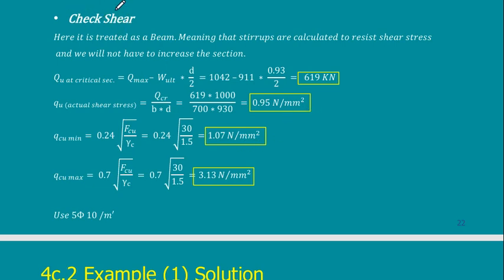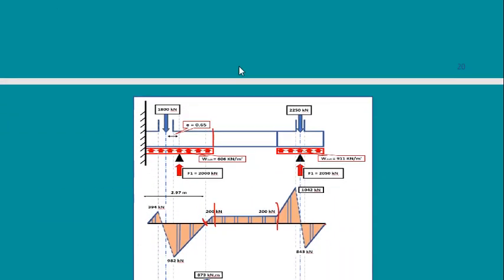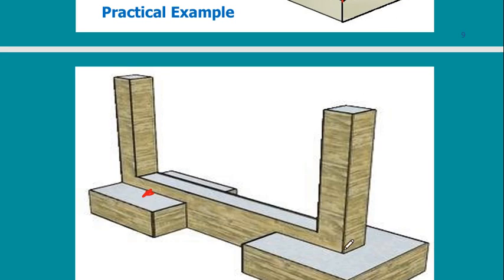So similar to what we said before, to check the shear, I go to my footing and check the locations where I need to check the shear. I can check the shear at this line. This is the maximum shear. I can check the shear at this line. Just a moment. I can check the shear at this line.